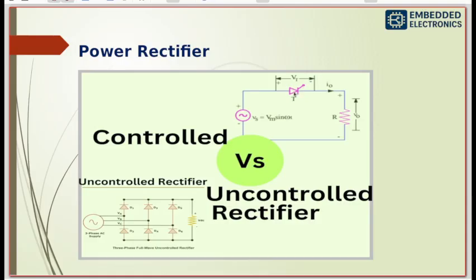Here you see, right? Even if the electricity is pushing in the right direction, the SCR stays closed until it receives a trigger or pulse at the gate terminal. So you can wait a few milliseconds before sending the trigger pulse. By waiting longer, you choke off part of the electricity wave, which reduces the average power going to the load.